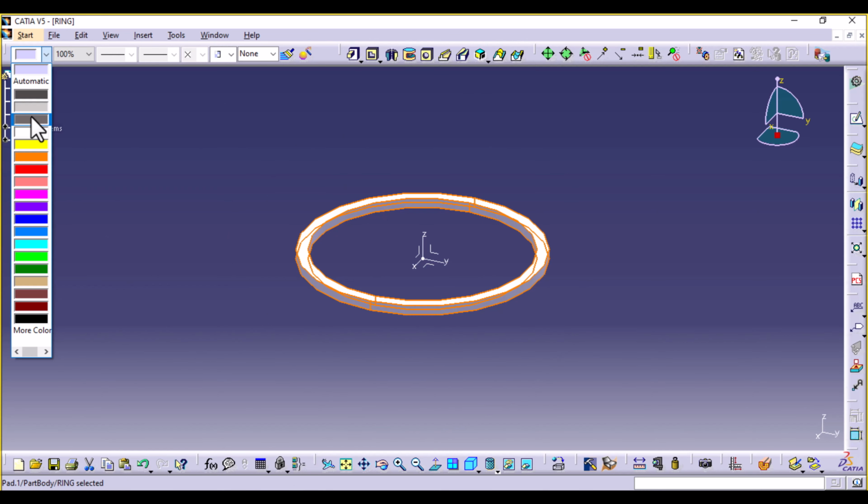And then select this outer edge. We're going to chamfer 1.3 millimeter in depth, and then 45 degrees angle. You can cross check here to see where the length is. Preview. Select OK.